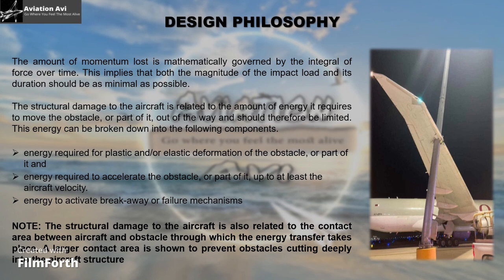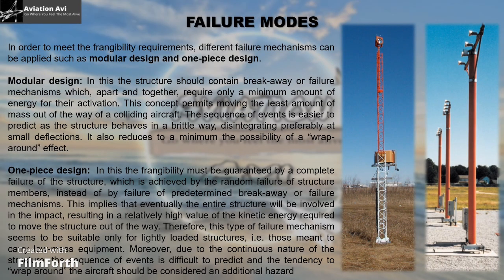A larger contact area is shown to prevent the obstacle from cutting deeply into the aircraft structure. So, in order to meet the frangibility requirements, different failure mechanisms can be applied, such as modular design and one-piece design. Number one, the modular design. This structure should contain a breakaway or failure mechanism which comes apart and together requires only a minimum amount of energy